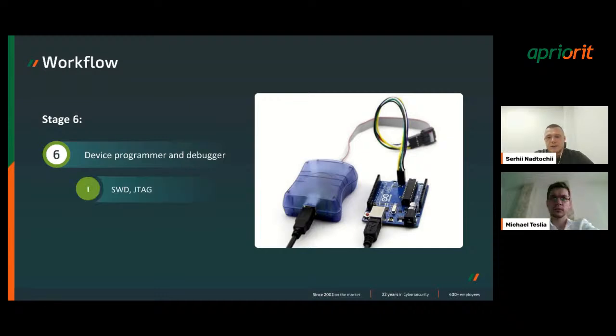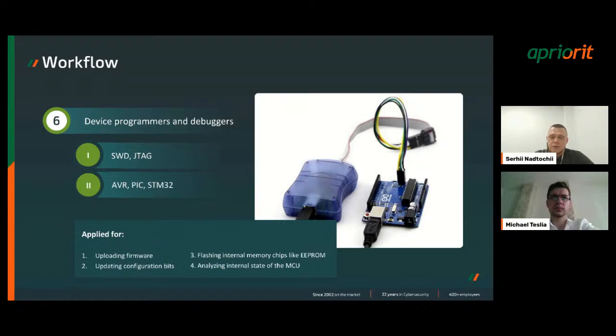So these devices are usually involved in the process. For example, a programmer is used for uploading firmware onto the microcontroller, updating some configuration bits, flashing some internal memories like EEPROM, and it can also be used to download firmware from the device.